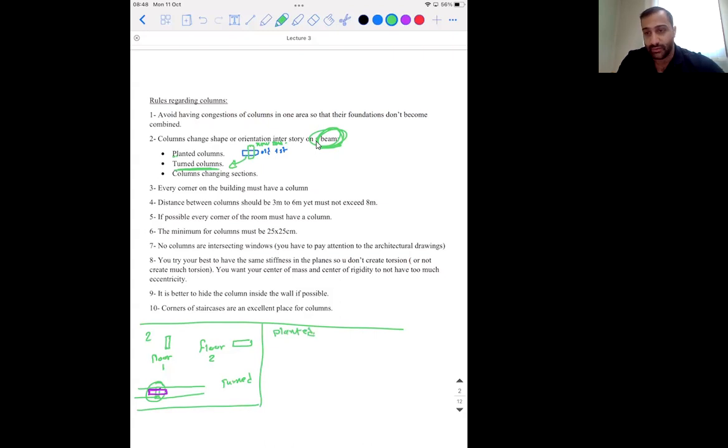Sometimes you have architectural regulations where you could place beams and columns on the periphery of the building, but that's not allowed through regulations to be on the periphery of the building on the second floor. So basically you're going to lose the columns that you placed on the corners of the building in the first floor. They should be connected, ideally. Ideally you want a column like that and a column like that on top of it, right? And this is like a story, my finger, yeah?